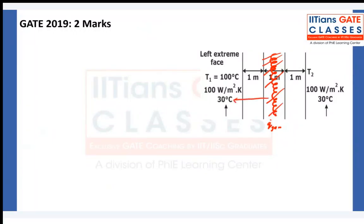So let's say it is Q dot conduction 1, and it will be conducted here as well, Q dot conduction 2. I am not saying they are equal. And it is steady state, so Q dot convection will also happen, and it will be equal to Q dot conduction 1, and here also Q dot convection will happen and it will be equal to this. So if I say Q dot generation, whatever heat is generated, equals Q dot conduction 1 plus Q dot conduction 2. Do you have any problem with this?